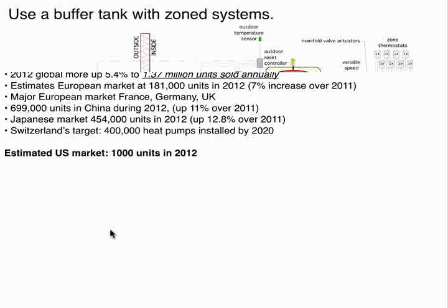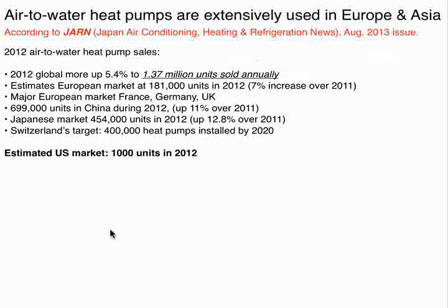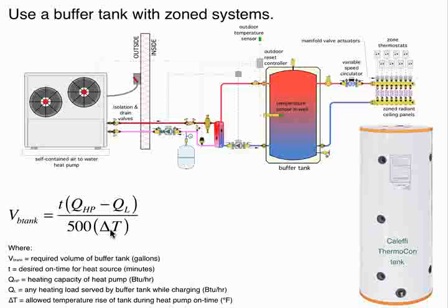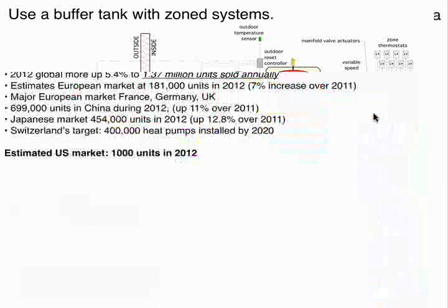Now, I mentioned earlier that. Hey, John, this is Mark. Back to that prior slide. One question, please, that came in. On the system side, is there an expansion tank that needs to be included in the schematic? Good eyes. Yes. There has to be an expansion tank. It's not fully detailed. Absolutely. You'll see there is an expansion tank over here on the antifreeze side of the system, but the water side of the system does need to have an expansion tank on it.